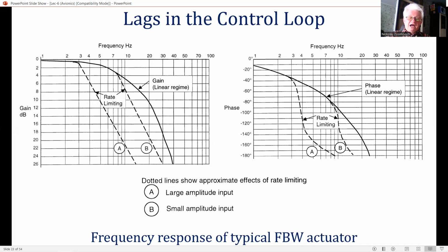The design of a fly-by-wire flight control system must take into account all the sources of lags which are present in the control loop, and accurately model the structural coupling effect on the flexural modes. Lags in any closed-loop system are destabilizing, and the significant sources of the lags are actuators, sensor dynamics, and noise filters, latency in the computational processes, and notch filters. These effects are briefly discussed as follows.